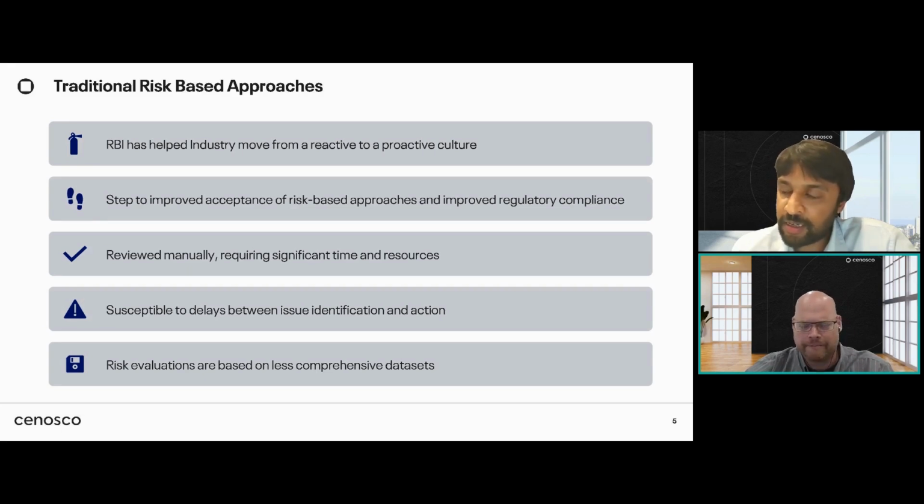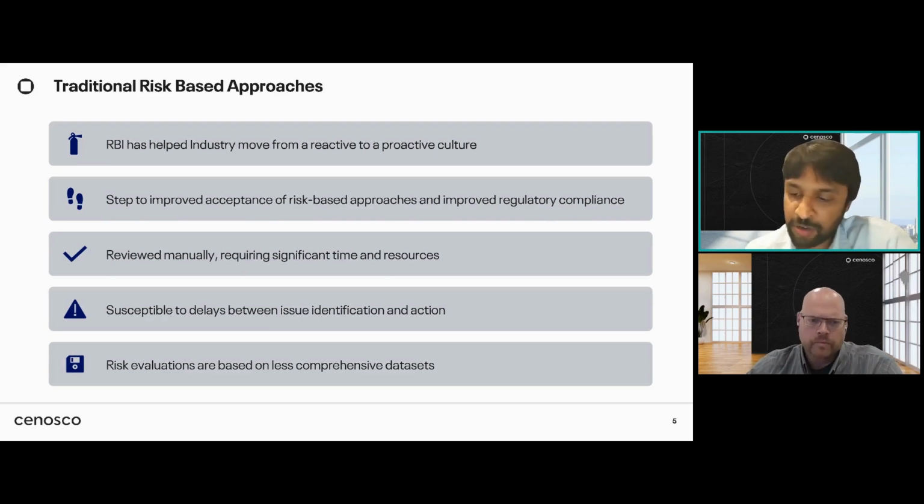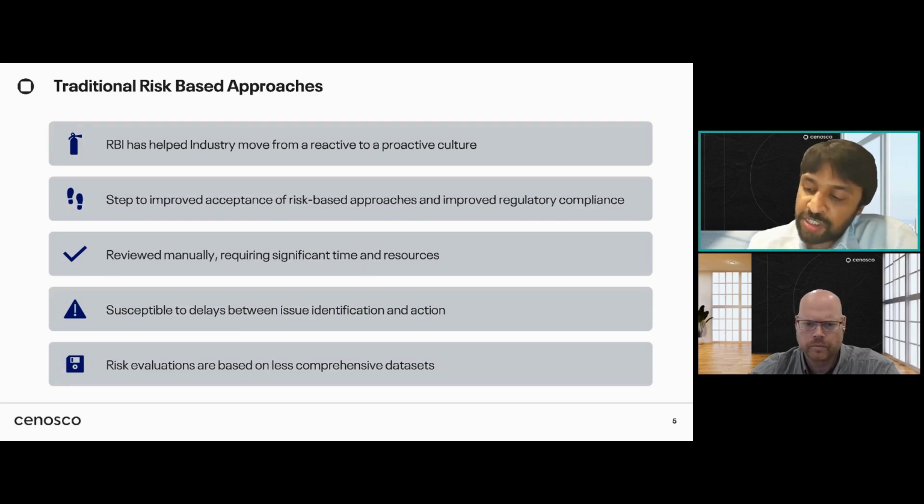Yeah, exactly. Operations could change, right? Processes could change. Ideally, in most cases, there should be a management of change process. If it's planned changes to operations and process conditions, sometimes it could be unexpected as well. But ideally, what is not happening with the risk assessment is that these changes in conditions could result in change in degradation rates, for example. And that degradation rate is not continuously used in terms of updating your risk assessments.